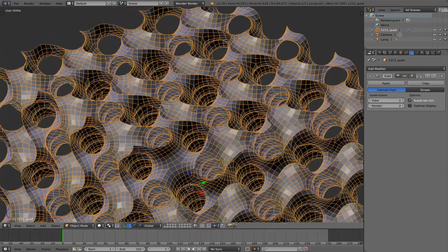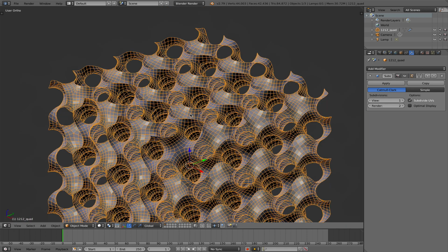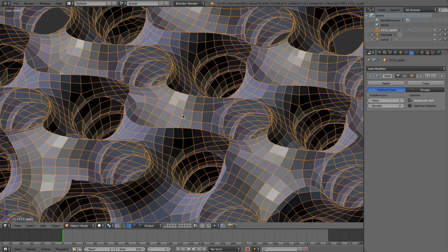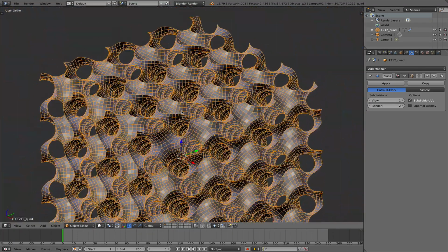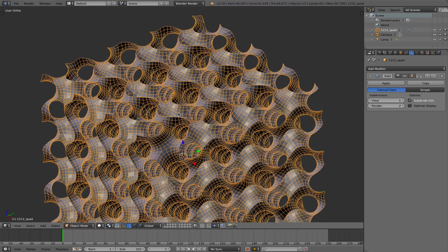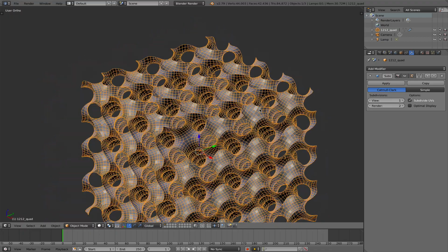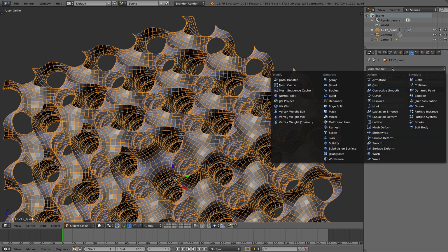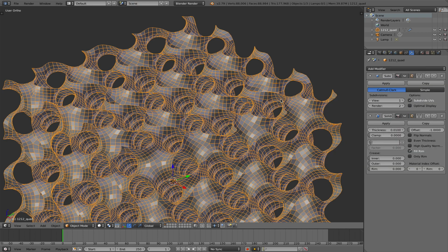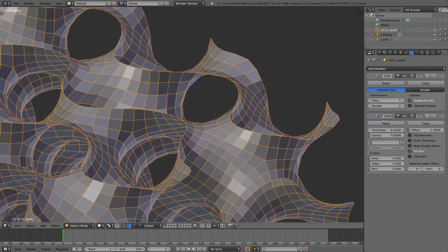Now, you could probably go ahead and export this into Fusion 360 and convert it into a surface. But the likelihood is that this would also not thicken as a surface in the patch environment. I haven't tried this out, but chances are it fails. So the next thing I'm going to do here in Blender is apply a solidify modifier. What that does is basically work like a thickening. And I can increase the thickness.